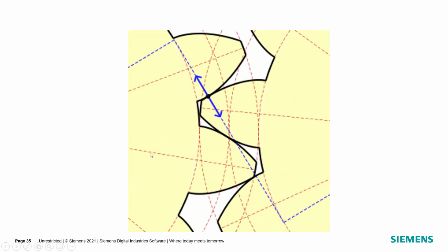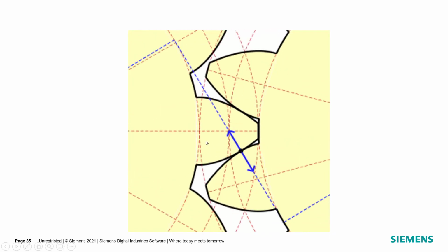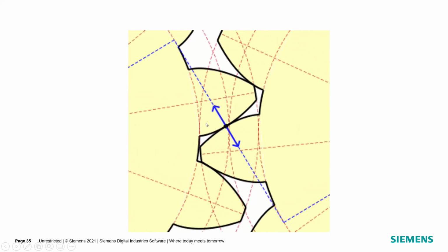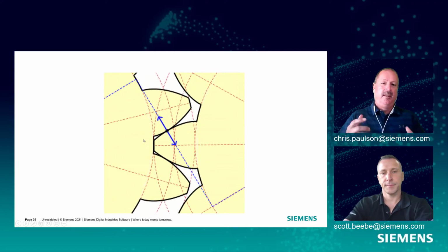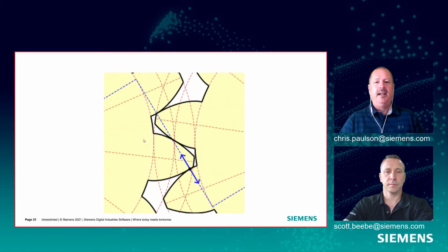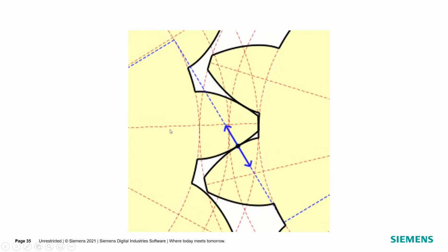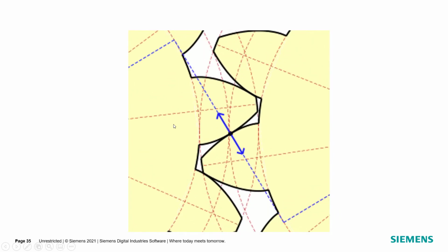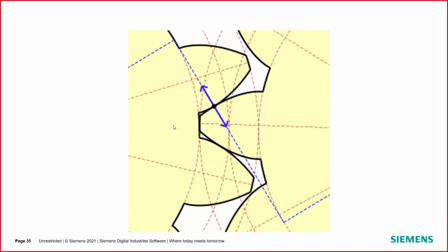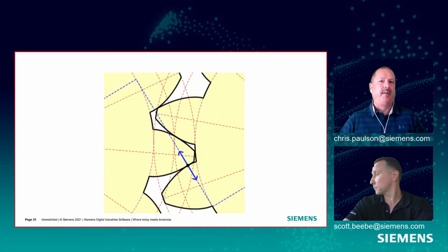One of the interesting things going on is the tooth on the left, when it first contacts, is going to be relatively stiff because engineers, we like cantilever beams. You load the beam close to the base, it's really stiff. As you transition out toward the tip, you're getting less stiff. So the gear tooth stiffness is going to vary during the rotation.